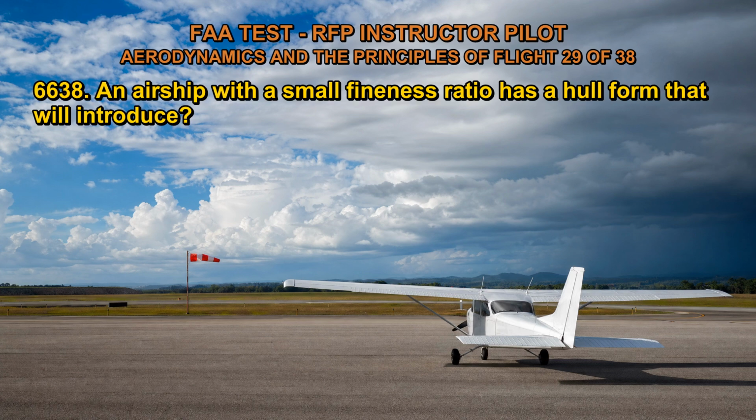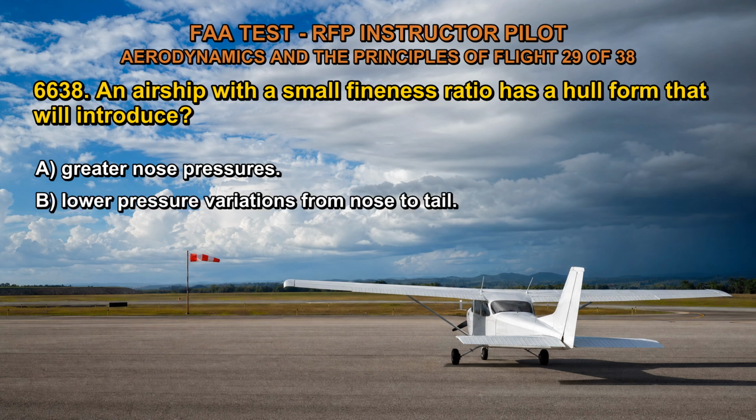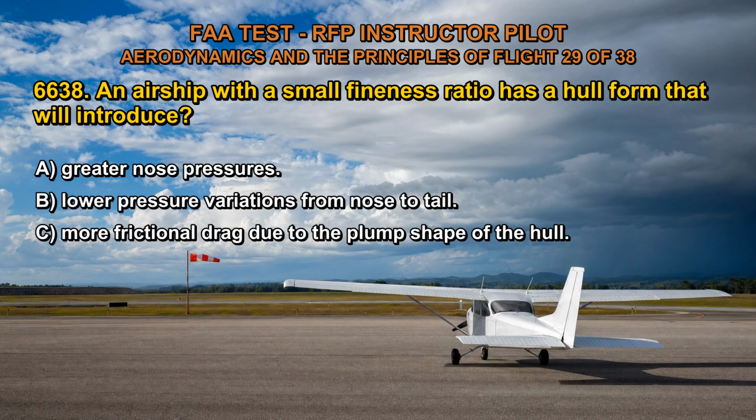6638. An airship with a small fineness ratio has a hull form that will introduce A. Greater nose pressures. B. Lower pressure variations from nose to tail. C. More frictional drag due to the plump shape of the hull. The correct answer is C.